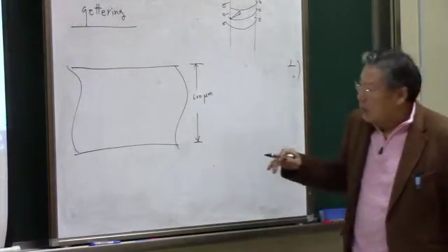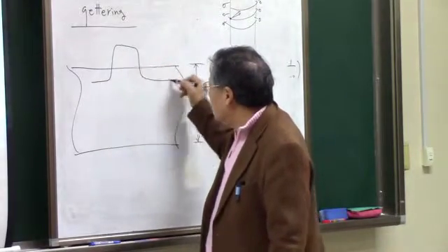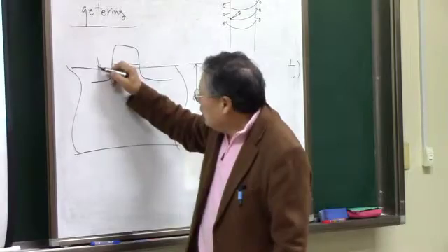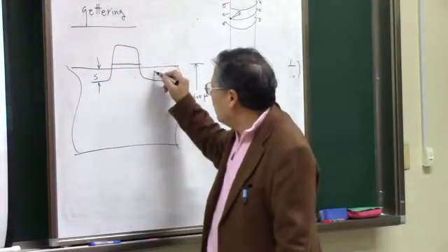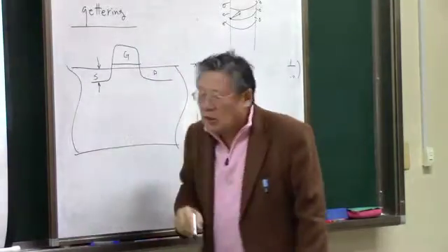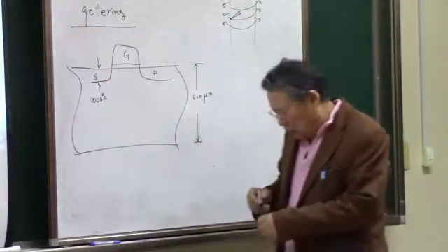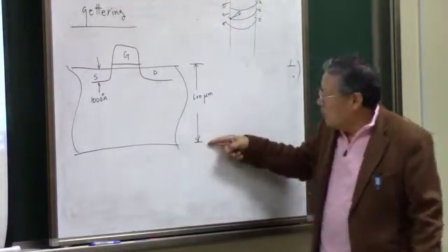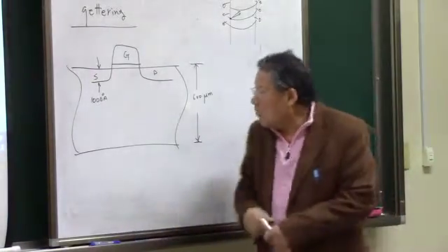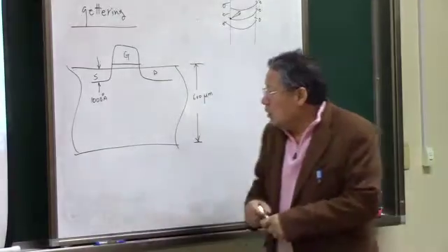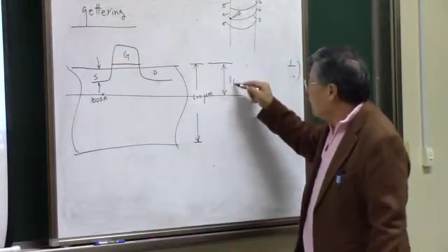So in order to prevent that, we have to maintain a certain thickness of the silicon wafer, and that is the 600 microns. Now, if you build the MOS transistors on top of this, with source, drain, and gate, the junction depth is typically about 1,000 angstrom, which means among this 600 micron thickness of the wafer, we just use at most the top 1 micron in depth.